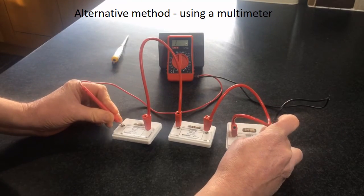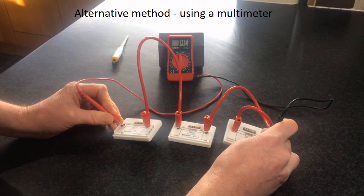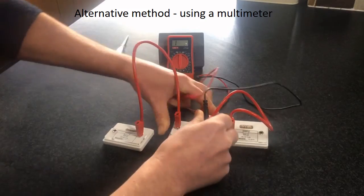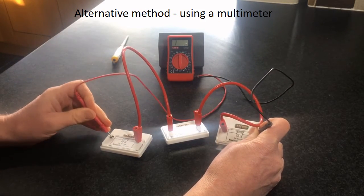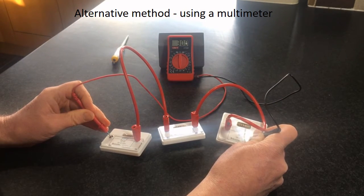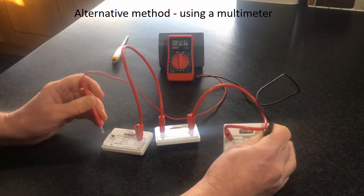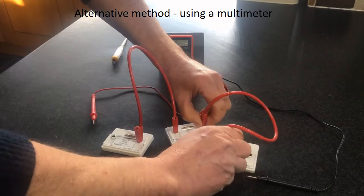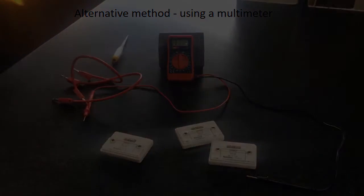Again, connect across the ends. Just waiting for it to settle down. 34. Just going to double check, trusting that I've got a good connection in those two. So it's still 34. Ah no, I had a slight poor connection there. I'm going to call it exactly 30.0. So 30.0 for the 3 of them. And that's measuring combinations of resistors in series.